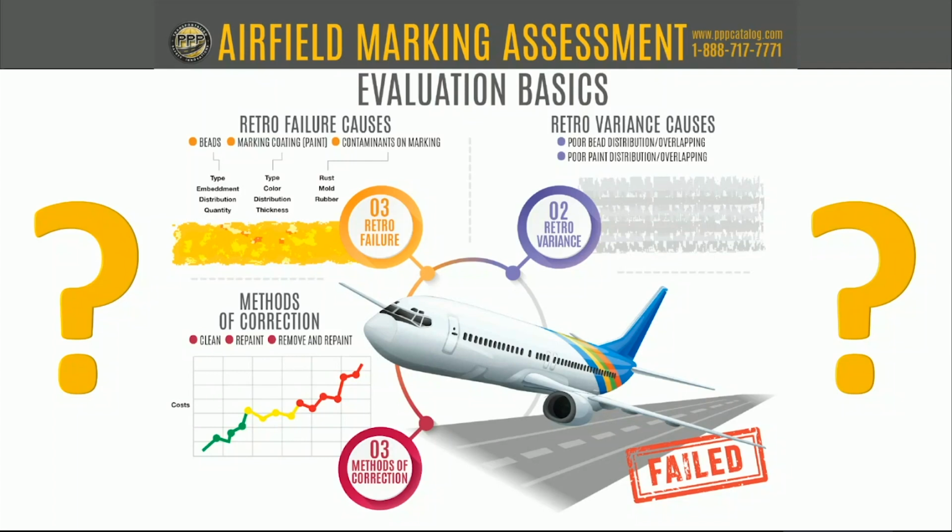Instead of a 17, you're going to starve that line if you're riding behind it. So you're going to have to jump that up into the 20s and maybe even as much as a 26 if you're blowing and going. And then, of course, if you're running a truck, then you probably already know the answer to it. But those are usually 26 plus. So that's what you'll find a lot of times. That's the tip variances. Mike, what's your thoughts on that?